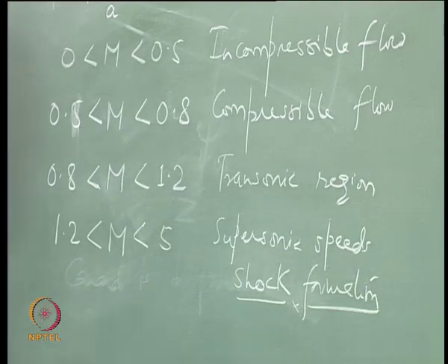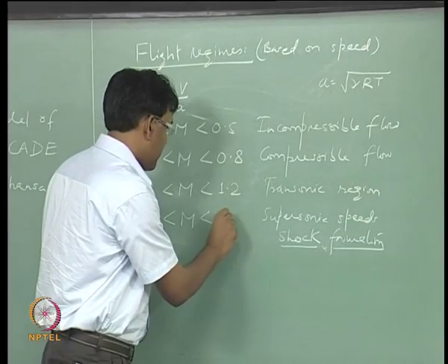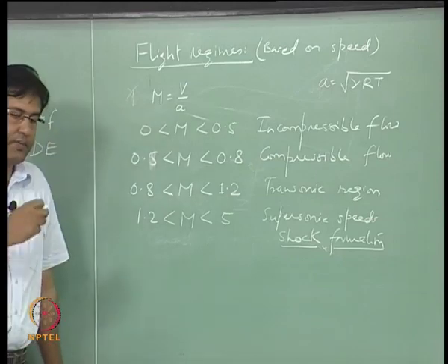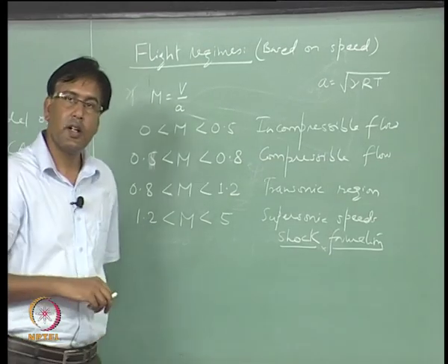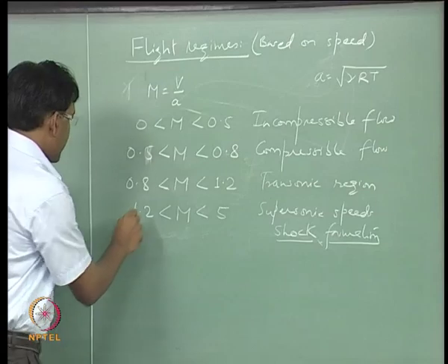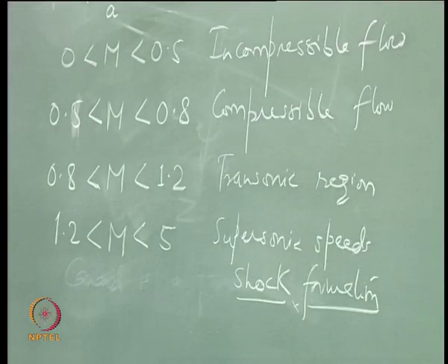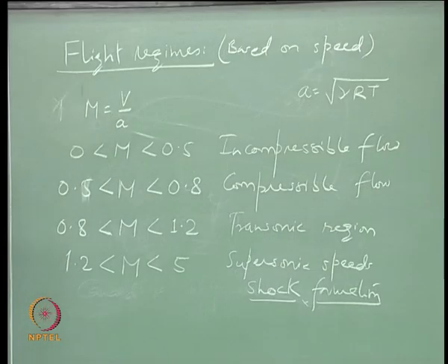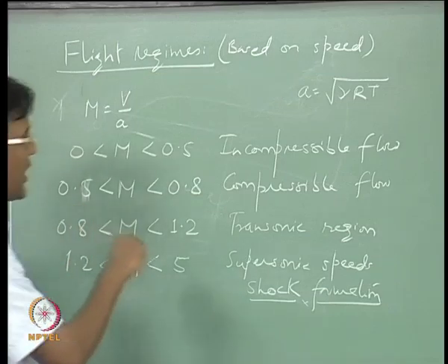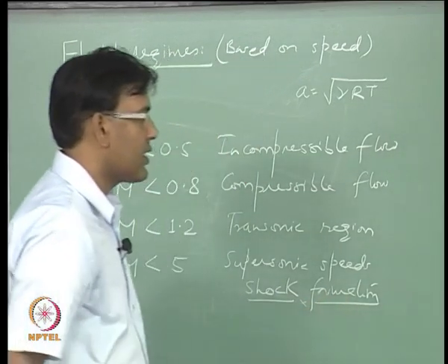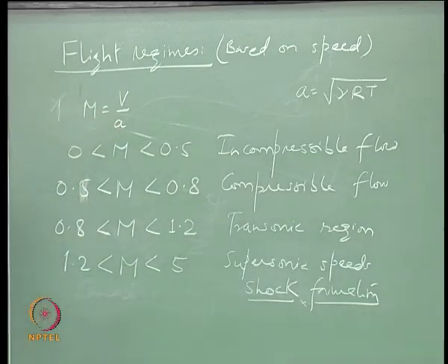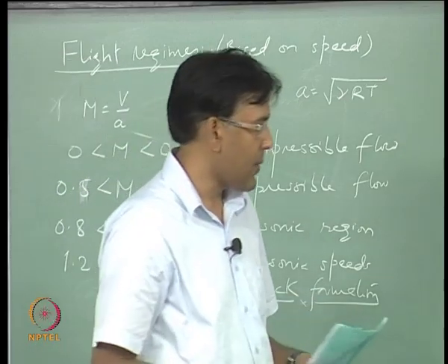If you do not want to talk about some low speed maneuvers, for example level turn and so on. So, these are the flight regimes that one can design the aircraft to fly in depending upon the requirements, and the choice of airfoil or the wing section is going to be dependent upon the speed regimes.